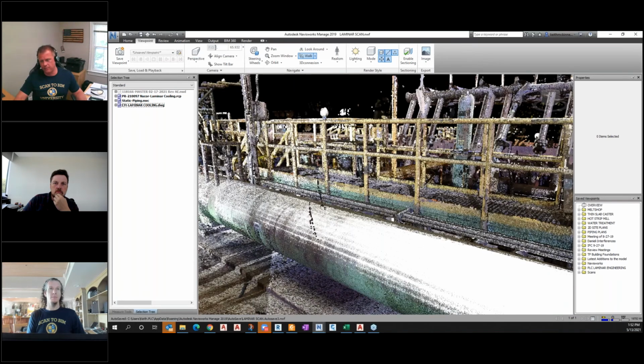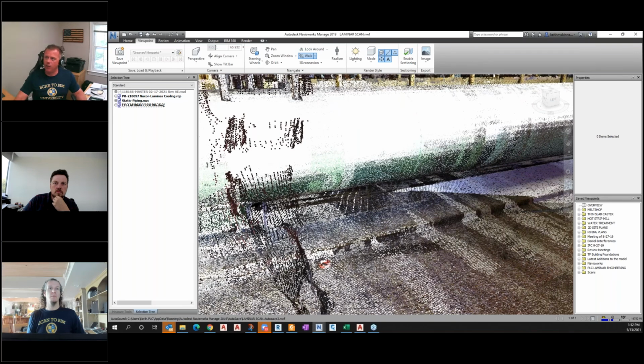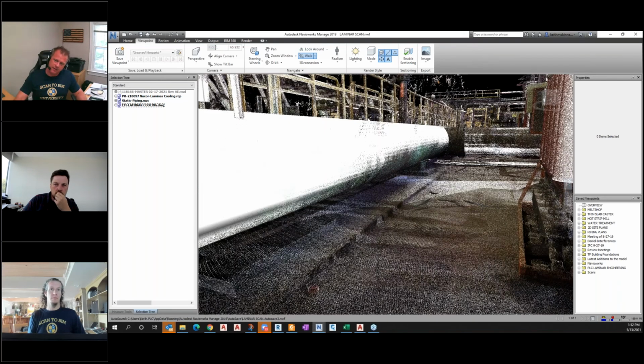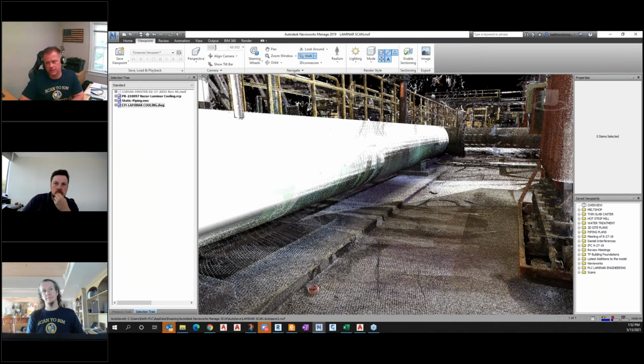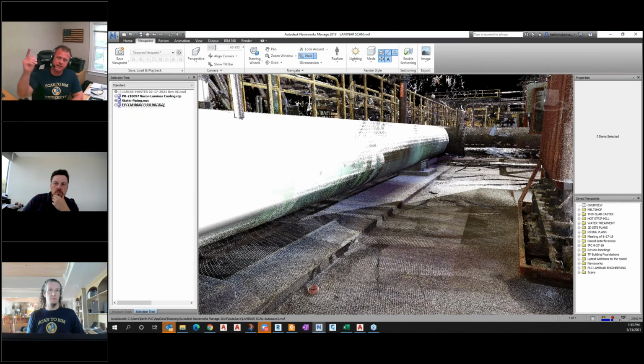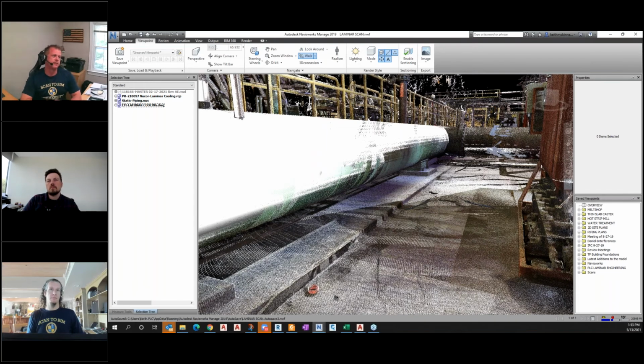So if I'm going to put a pipe support stand down here, it may work fine on the south end of the project. Down here, it may be 7 inches of grout, which could be costly. Or I could have it the other direction, where I've got all my supports built, they fit down on this end, but they won't even fit down there because they're hitting the concrete. Because most people just work in the perfect world of design, saying, oh, that's all level. Well, it's not level.